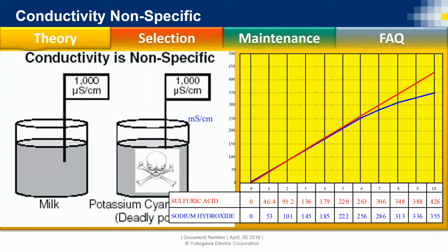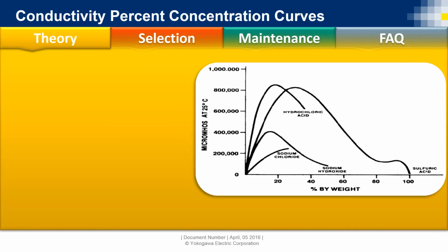So here, at a certain point when you're in the lower range, sometimes we may use pH measurement along with conductivity to know, okay, is this 50 millisiemens I'm seeing because of sulfuric acid, or is it because of my base, my alkaline solution? So we just need to know exactly what we're measuring. And I'll show you in just a moment why.